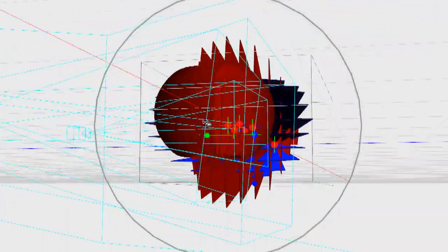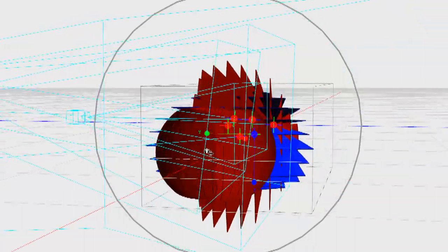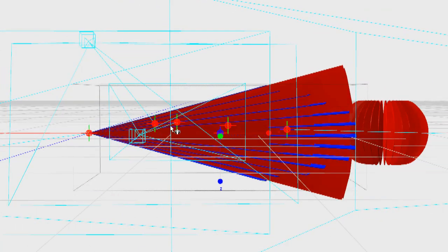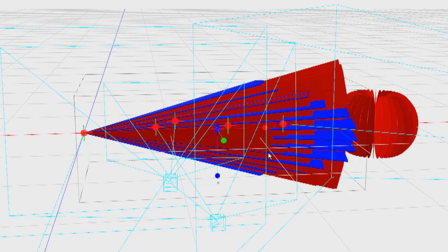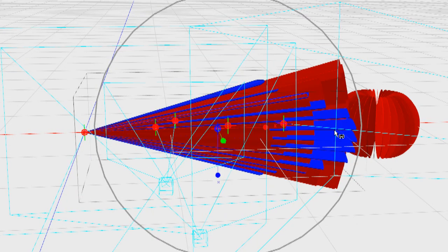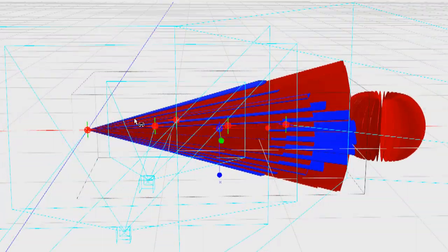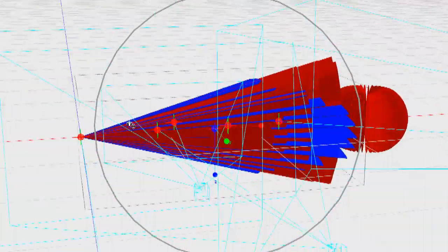So two separate Yagi antennas just rotated 90 degrees from each other will give us the same that we had with the diversity antenna, remember? Which is a bit more convenient because it's got two antennas built into the same package. One's horizontal, one's vertical. But this assumes that we have two Yagi antennas right next to each other via a diversity receiver, which shares a slightly different orientation of the beam pattern.